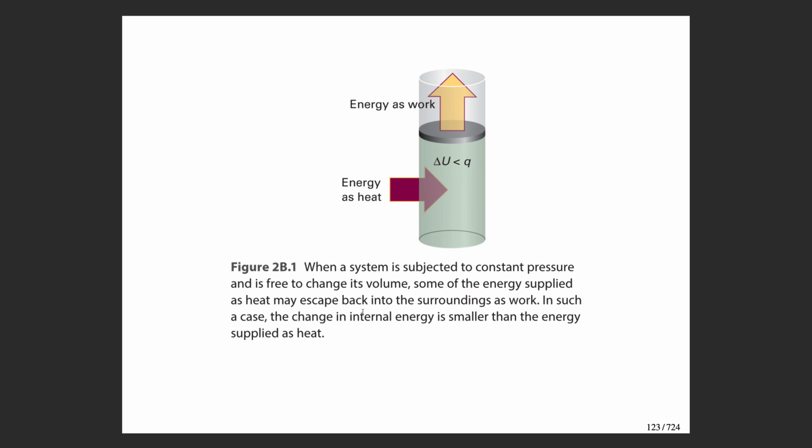So suppose that you have a system that has a constant volume, so a rigid container, and you transfer some energy to that system. What will happen is that the energy that's transferred in, say as heat, will go directly into changing the temperature of the system and the internal energy. And so you'll heat up the system, of course. Now, when the system has the ability to change its volume, okay, so when volume is not constant, but rather when pressure is constant,